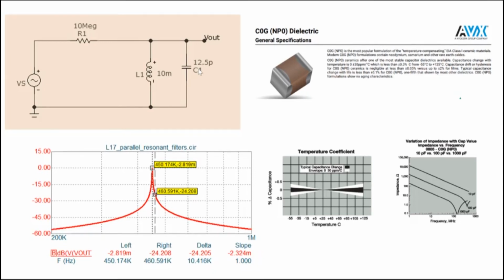So one uses special capacitors. For example, you can see here, these are capacitors which are called NP0. They are temperature compensating capacitors here. So the capacitors and inductors have to be as much as possible independent of temperature. But despite taking all possible precautions, you can see here the percentage change in capacitance as a function of temperature. So these are very special capacitors, temperature compensating capacitors.